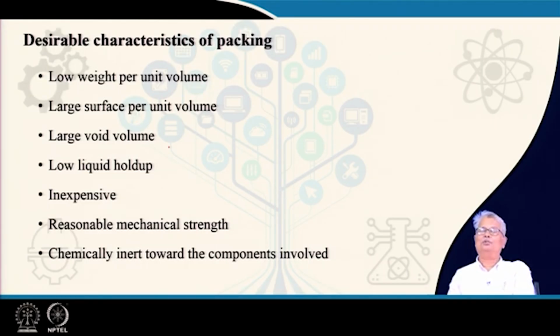The packing has to survive its own weight, the tower packing. So, naturally, it must have a reasonable amount of mechanical strength. It should not get crushed by its own weight. Not only that, there is another thing which requires the mechanical strength to be high, that is, when you fill a tower, there are two ways you can do it.